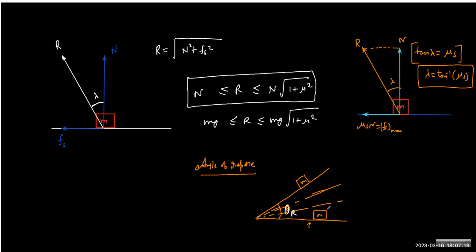And what is really interesting is that when it is repose angle, then the friction must reach the limiting value, right? Mu s N, correct? And mg will act like this. And it is about to move, which means the friction is at limiting value, but it is not moving, so it is still at rest. So what should be the direction of surface contact force at this instant? Who will tell me? Vertically upwards.